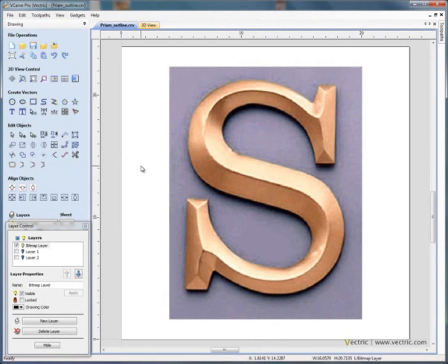Hello, this tutorial will explain how to use the raised 3D prism machining toolpath options available in Aspire and VCarve Pro to carve decorative raised lettering such as this letter S that we have here in our two-dimensional view. These are the sort of letters that are typically carved very large and into very thick materials. You'll see that the edge of the cutter is used to form the shape on the letter.